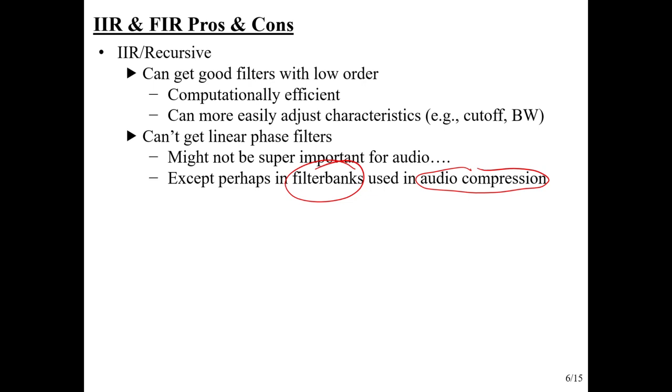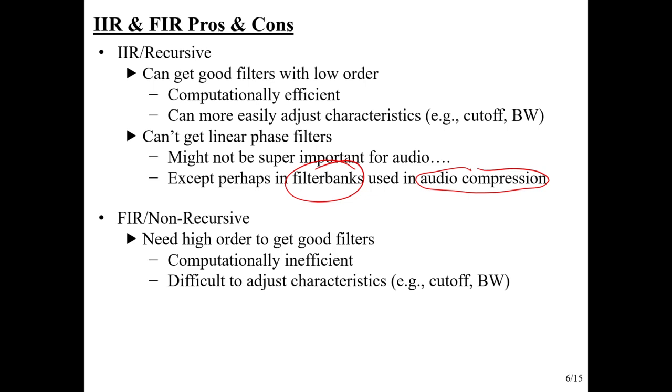So there we often focus on FIR filters with linear phase, but for the most part, we don't worry too much about linear phase. If you think about it this way, all the classic analog audio stuff that everybody loves how it sounds was all built with RLC circuits, and those don't have linear phase, so maybe we don't really need linear phase in most audio applications. Okay, so that's IIR. There's some good and maybe some bad, but not that much.